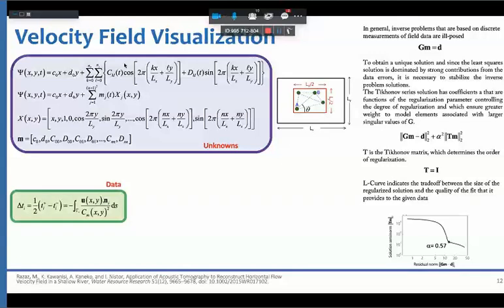So these are your unknowns, and we're using the stream function because it reduces the number of your unknowns. Of course, you can solve and write the equations for the U and V, but you're going to end up with too many unknowns, and you should always consider that the number of knowns, or the delta T, along the path is very limited. In this case, we have 16.